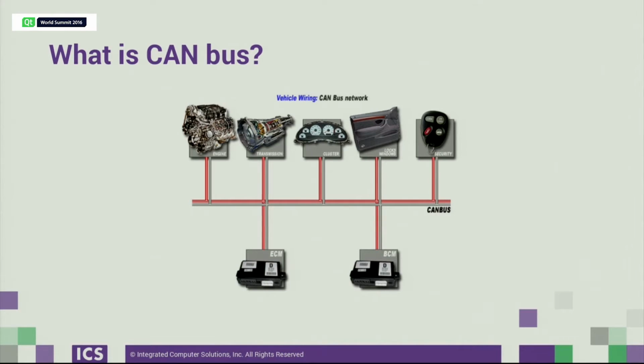So it was originally developed by the company Bosch, and it's now been standardized as a series of ISO standards. So in your typical automobile, you could have as many as 70 CAN bus devices throughout the vehicle. So it's widely used in vehicle systems, but it's also being used for a number of other applications in embedded systems, industrial applications, different types of medical devices, in fact. I've even seen it used in some high-end bicycles.